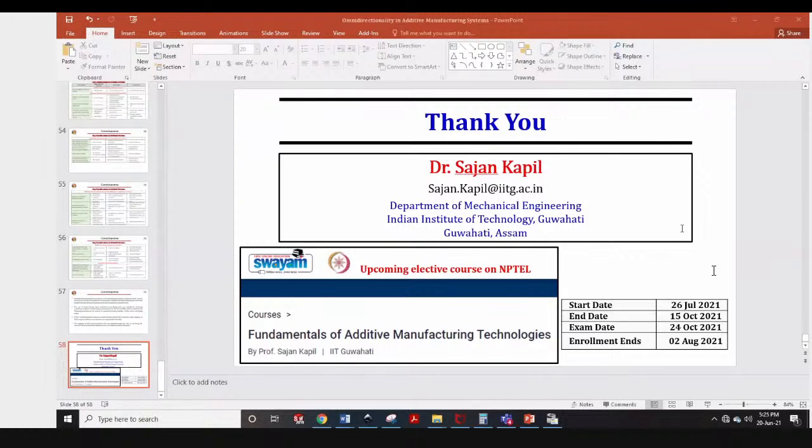If you are rich, select the laser. If not, select the MIG. When I joined here, I also started with MIG. Let me put it in a scientific way. If you are dealing with ferrous materials, go with MIG blindly, no issues, and you are not really worried about the material being expensive. MIG can give you a very high deposition rate. No other process can give that.